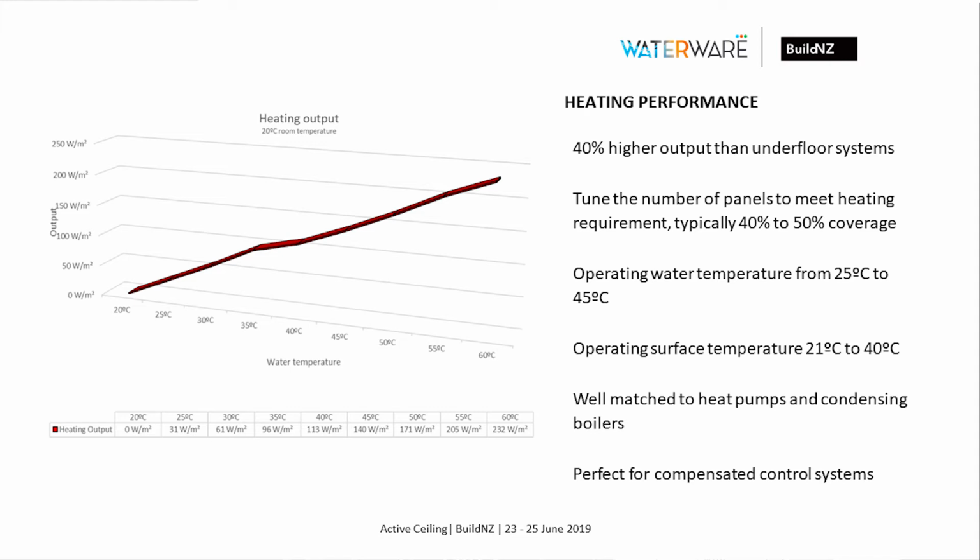So you can increase or decrease the heat that you put into the building by making the water temperature either higher or lower. What a temperature compensation system does is it measures the outdoor air temperature, makes an estimation for how much energy is required in the building, and then it electronically changes the water temperature up and down to compensate. The advantage of the system is you increase the COP of your appliance, so your efficiency goes up, but you also increase the comfort in the system.